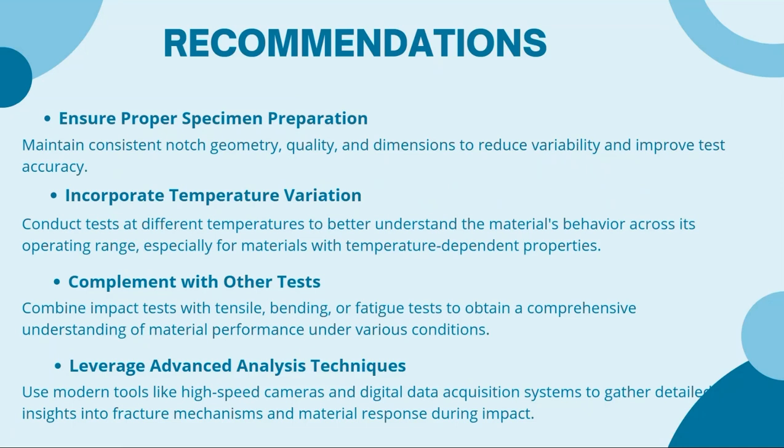The last one is to leverage advanced analysis techniques, where we can use modern tools like high-speed cameras and digital data acquisition systems to gather detailed insight into fracture mechanisms and material response during impact.